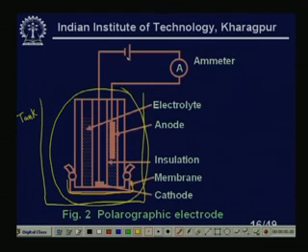Now, for a fixed bias, for increased concentrations I will obviously get higher relative current outputs, which will be utilized for the measurement or control of the dissolved oxygen partial pressures in the liquid, clear.